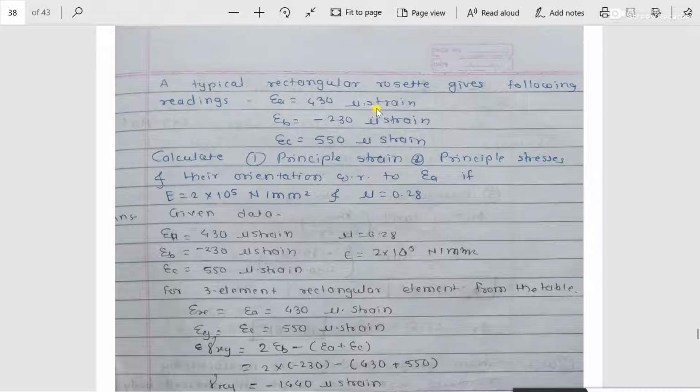430 microstrain, it is given in microstrain. Then epsilon b is minus 230 microstrain. Epsilon c is given as 550 microstrain. Then I have to calculate the first parameter, the principal strains, that is epsilon 1 and epsilon 2. Then the principal stresses, that is sigma 1 and sigma 2, and their orientation, that means the direction of the principal strains and principal stresses, that is phi 1